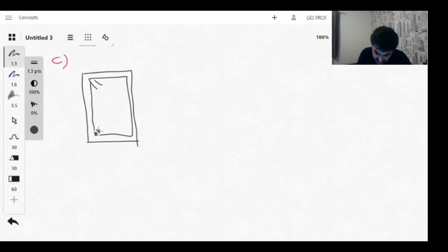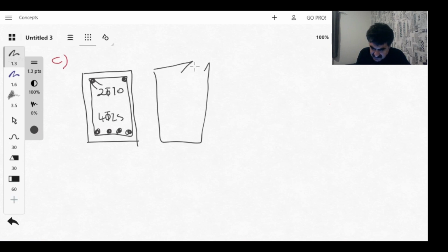And then we will have 4 rebars here, this is 4 by 25, and we need to put minimum 2 bars. This will be minimum 10 millimeters, 2 bars of 10. Okay, and then the stirrup will be like this. We can show it like this. It can be, for example, 8 millimeter diameter, with 100 millimeters distance between the stirrups.